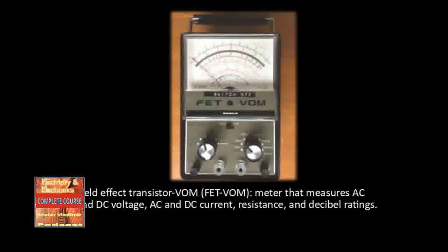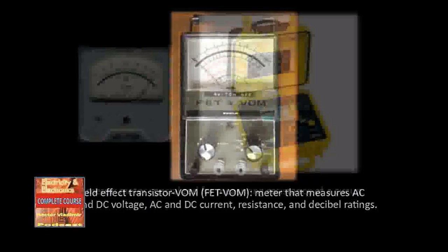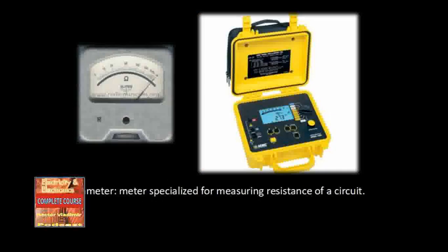The leads of the temperature probe are inserted into the meter, while the probe itself can be placed in front of an air conditioning duct, near a furnace heater, or submerged in hot liquid. The scale of the meter reflects the temperature in Celsius and/or Fahrenheit. The optional accessories for VOMs include adapters for reading higher than normal voltages and larger than normal meter current values.